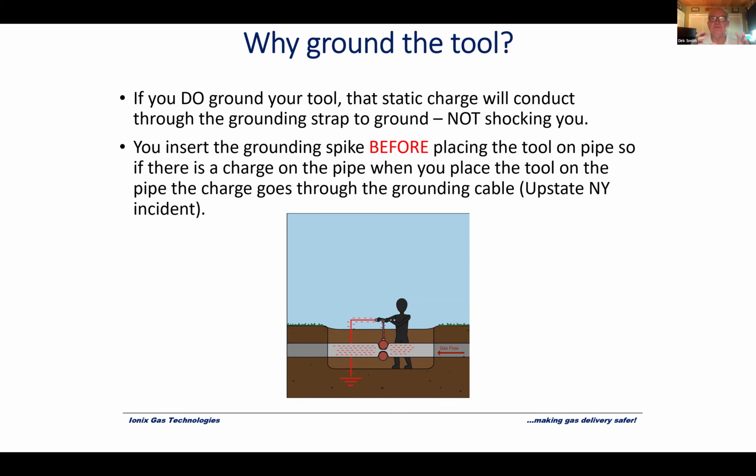Now, if you do ground the tool, then that charge, if it happens to arc through the pipe that's been generated by the squeeze off, it will go through the grounding spike, through the tool, through the grounding spike to the ground. And as James said, it's important to make sure you have good contact. Take some water when you spike it, pour some water in there to make sure you've got a good connection.